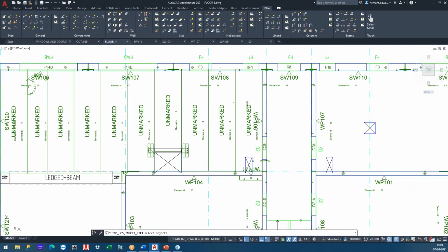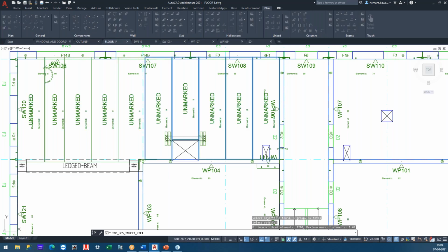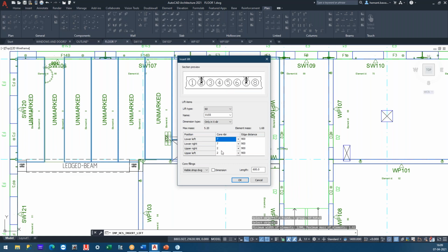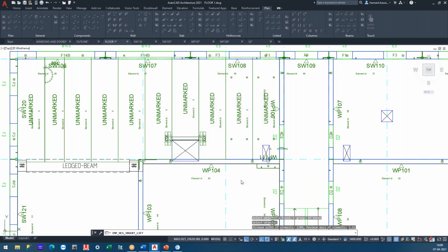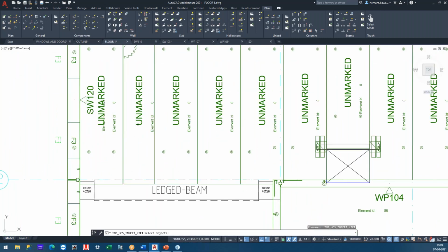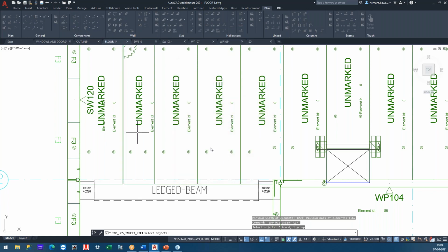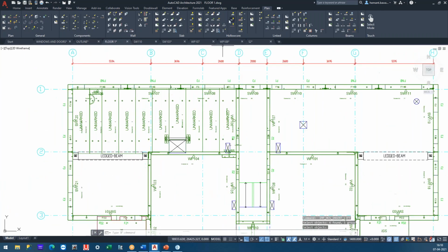And let's add the lifters to this hollow cores along with the core fillings. I will add it to the core 7 and core 2. We can of course change this if we like, and I will like to dimension them on the shop drawings. Okay, as you can see, I didn't select this one because this has a different width, so I will select it separately. And for this I have different core fillings to be added. Again the dimension. Okay, and let's just save it quickly.